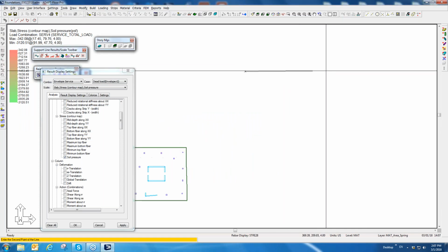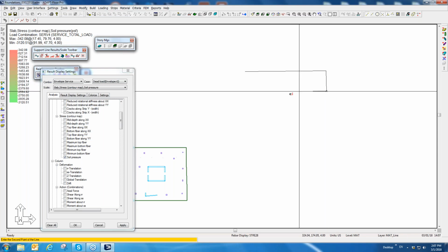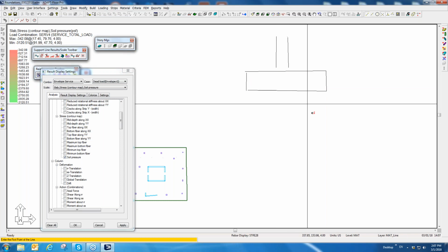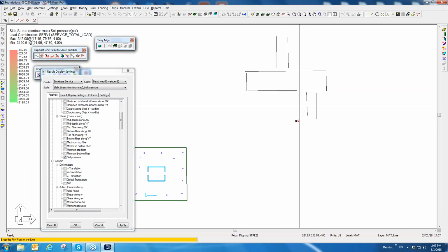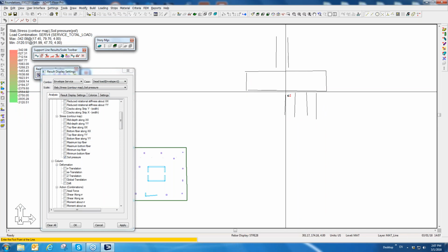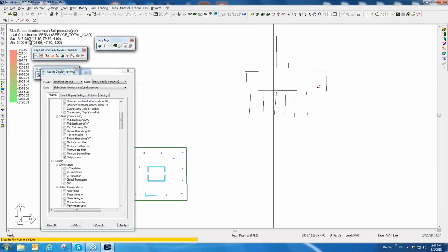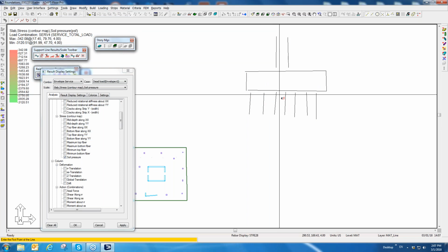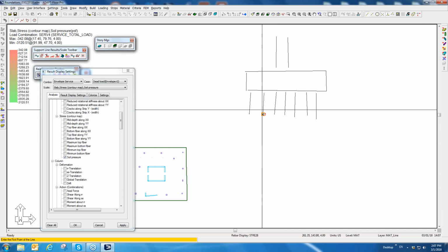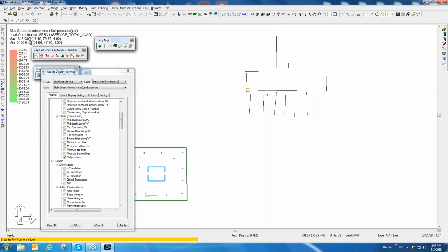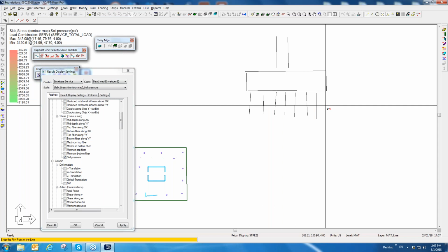Okay, so let's say this is a pile cap, and in the program you have a column that stacks on this cap, and then underneath the column you have several piles. In order to check the punching, it is typically checked based on the pile reacting against this cap, not necessarily this thing pushing down on it, though it probably should be checked for both. In order to get the check made for these piles punching through the cap, you must model these as physical components in the program.